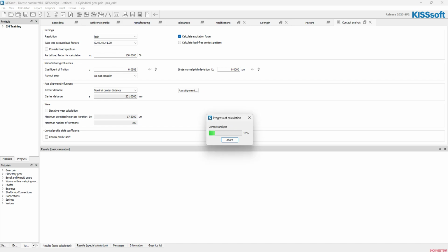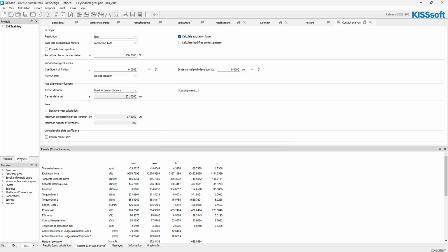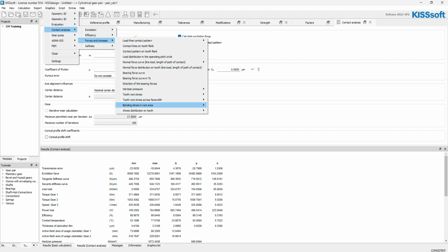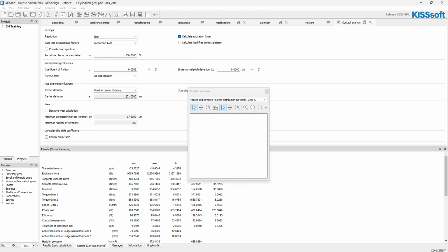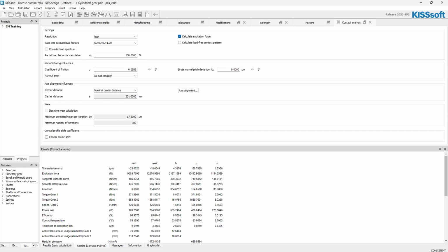So anyways, the point of the little video here is I want you to understand that with KISSdesign, you can migrate some of that legacy data and create your full system gearboxes pretty quickly. So this is 15 minutes of a little bit of work, and I'm able to get a pretty good grasp on what I think my tooth contacts are going to be in this particular design. And if I were to open up a shaft file, I would know that that shaft is bending or deflecting a certain amount, and it's giving me this contact pattern. And then from here, I can optimize with modifications.